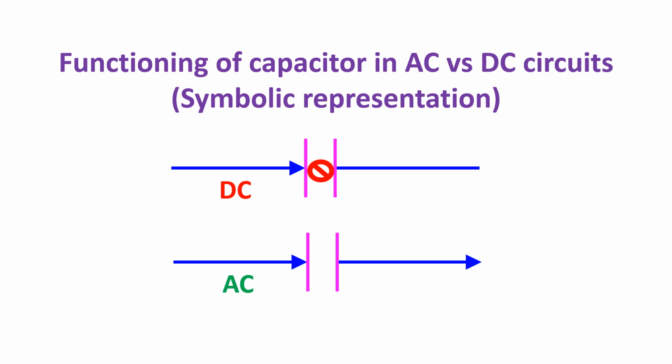When a capacitor is connected to a circuit with direct current supply, it will allow current to flow till it becomes fully charged, usually a fraction of a second, depending on the capacity of the capacitor. Once fully charged, dielectric does not allow further flow of current through the circuit. Initial flow of current is only to charge the capacitor plates and not through the dielectric when the voltage applied is below the breakdown voltage. Beyond the breakdown voltage, the capacitor gets damaged and may produce short circuit.